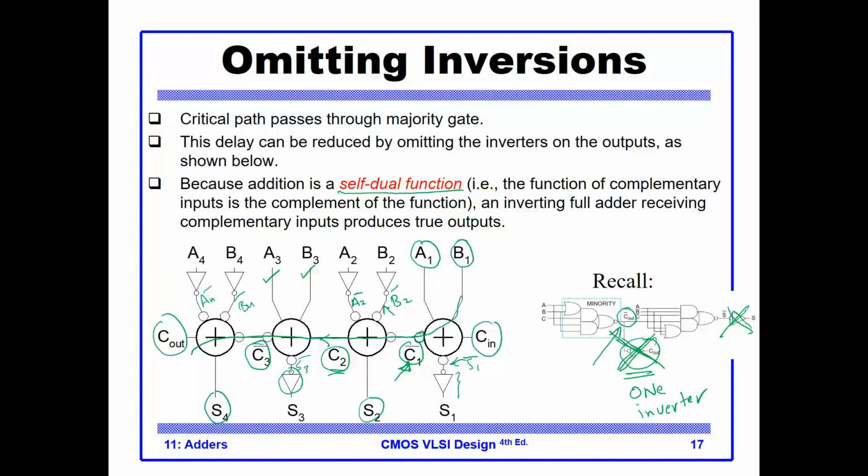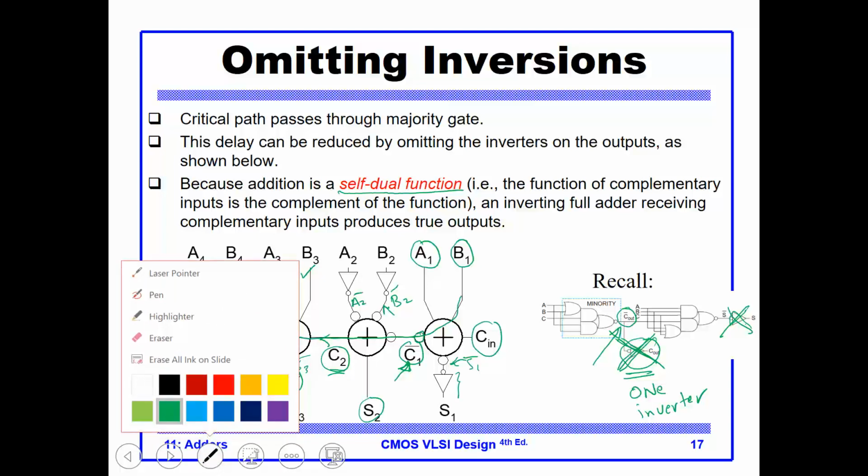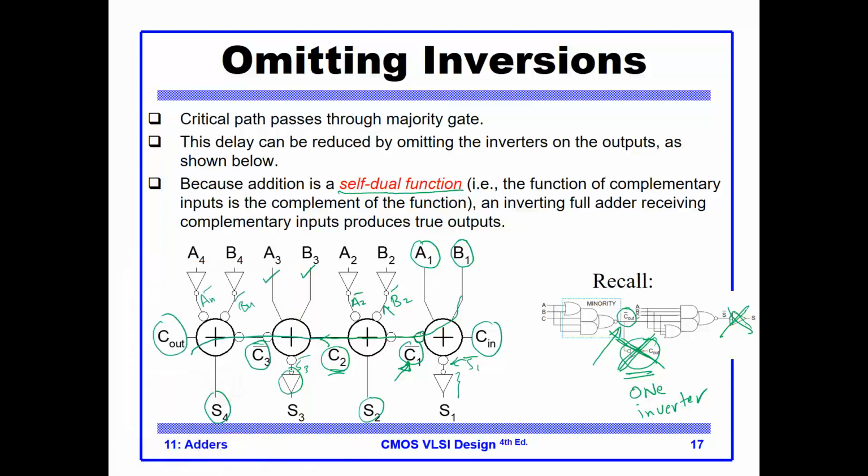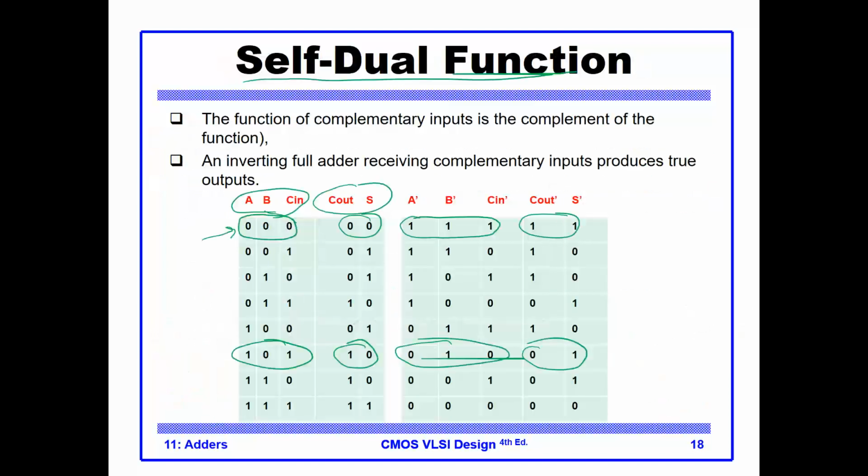Well, what I gained is that I saved here, let's do a different color, I saved here in this delay one inverter for the carry, another inverter for the carry, another inverter for the carry, and another inverter for the carry. So I saved in this delay 4 inverters. So let's go back to our original.